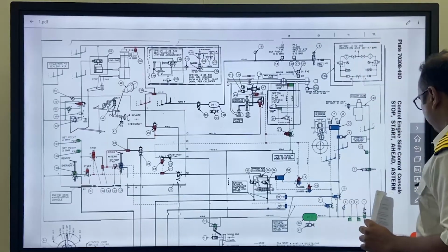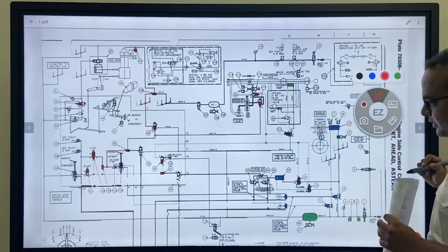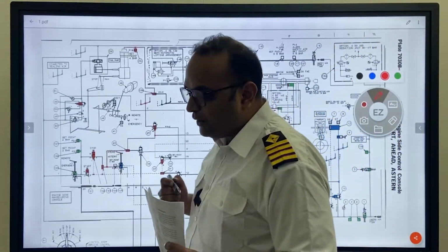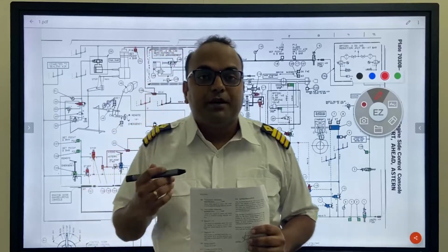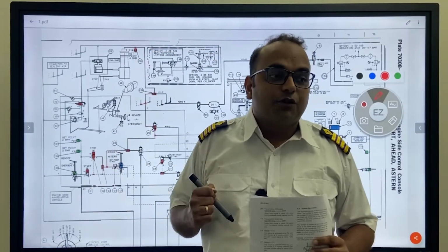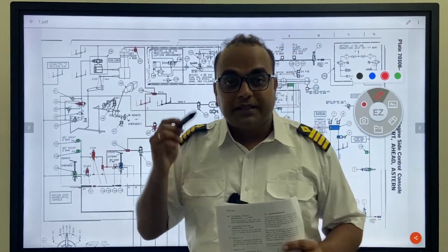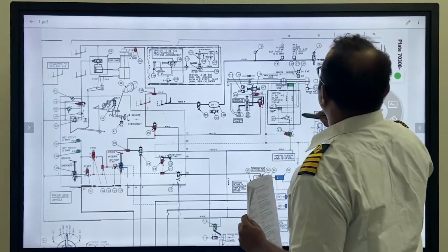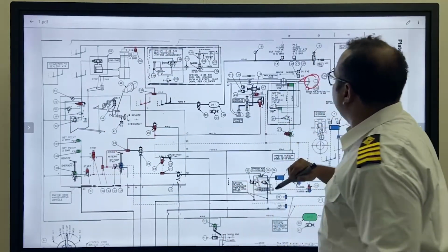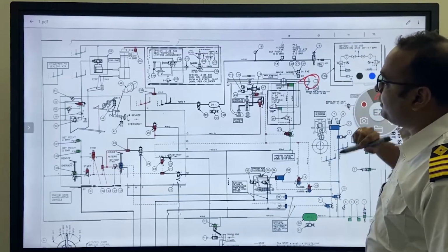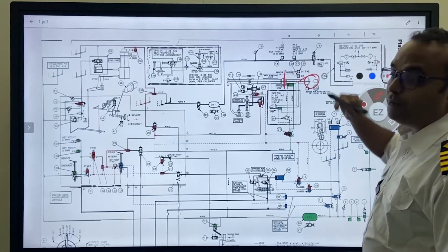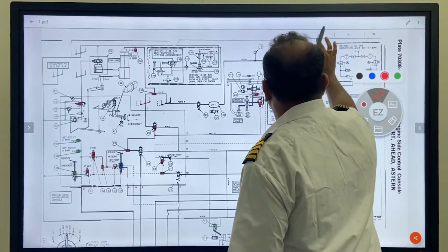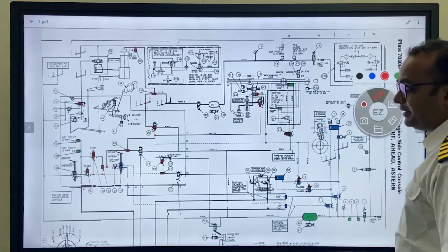Okay, we have a few types of air. We have main 30 bar air, which is coming from the main air bottle, and that air is going inside the main engine. That point is here. It is a supply of 30 bar air and is stopped by the main air starting valve. Fair enough. So we have 30 bar air here.